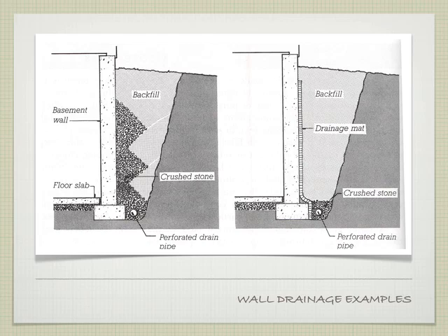Something a lot like this, which I'll pass around. It's a plastic material that would go up against the wall, and I'll pass this around so you can see it. When water comes against it, the water would then enter one of the cavities that's in it, which you'll be able to see, and drain down to the drain, which allows us not to put as much rock. We can just do regular backfill. That's why it's coated in this filter fabric, to keep the fine dirt particles and stuff out. So that's just a different example for how we're keeping that away from the building itself.